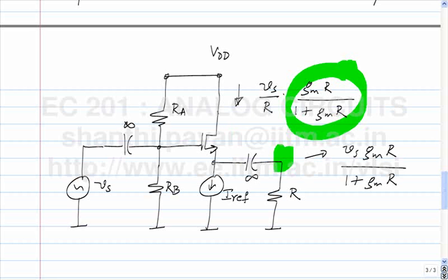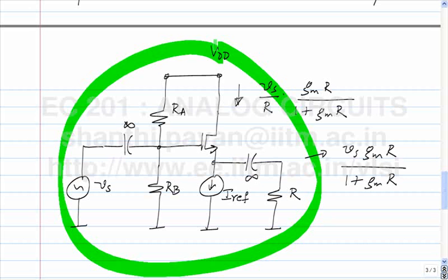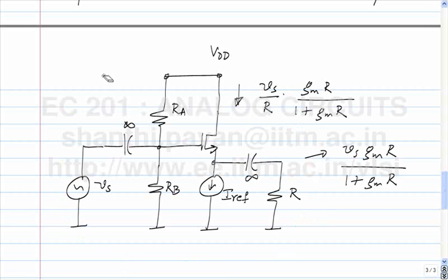So this gives you a way of implementing a voltage controlled current source where the properties of the voltage controlled current source are independent of the device itself, which is a very good thing because the Gm of the device can vary all over the place. But as long as it's sufficiently large, the transconductance, or the incremental output current by the incremental input voltage, is very nearly equal to 1 over R. And whenever you see things like this, you can be quite sure that there is a negative feedback loop hidden somewhere doing a very common circuit.